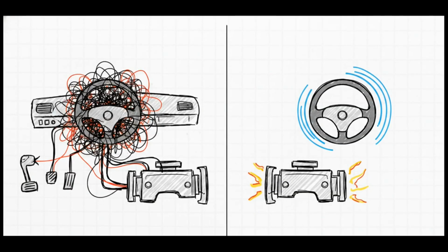To really wrap your head around this, think about driving a car. Imagine if every single time you turned the steering wheel to the left, your engine's RPM suddenly spiked, and every time you turned right, your brakes slammed on, right? That coupled behavior would make driving a literal nightmare. That's exactly what trying to control an AC motor without FOC feels like. Adjusting the torque inherently messes with your magnetic field flux, but by decoupling them, we're essentially separating the engine from the steering wheel. We can demand massive, instant changes in torque, and the field flux linkage isn't affected even a tiny bit. This is what gives us that dynamic, lightning-fast torque response.